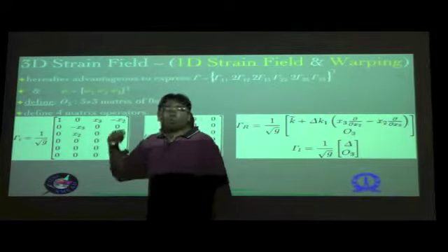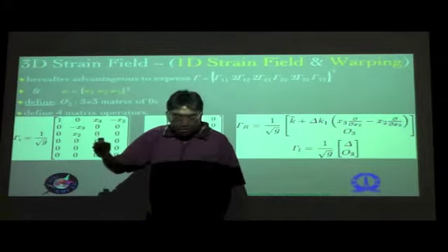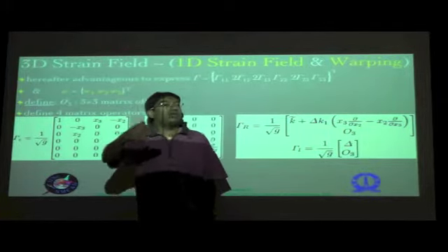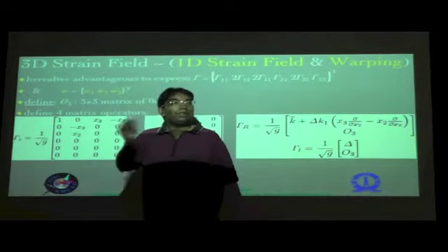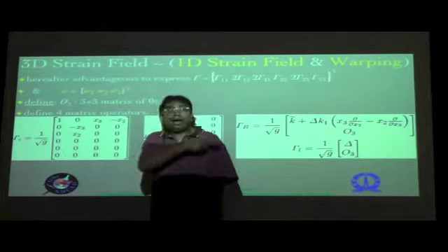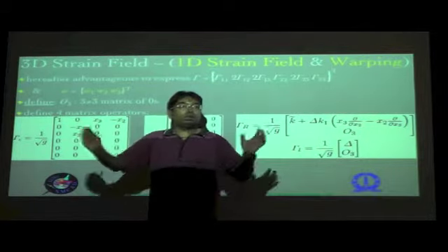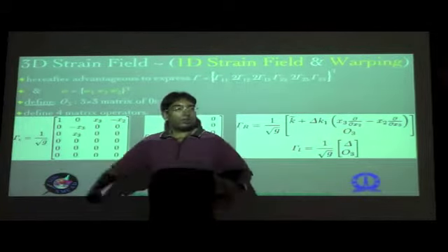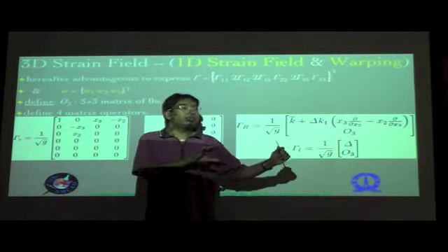The gamma, of course, is determined in exactly the same way as we did before, that is by determining the contravariant basis vectors for the undeformed configuration, the covariant basis vectors for the deformed configuration, juxtaposing them and then taking the dot products in a mixed basis. You have the expansions, but after expanding it, we can sort out those terms in each one of those expressions in such a way that we can lump them into 4 kinds of terms.